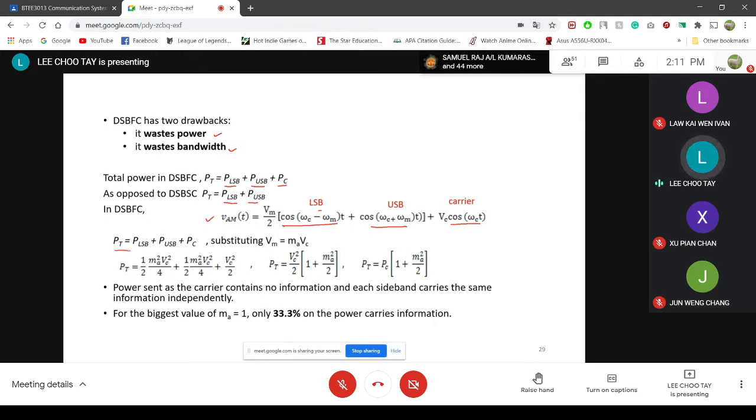So using this equation, the power in the lower sideband basically is this one. This is the peak amplitude of this lower sideband signal. To find the power in the lower sideband signal, basically take the peak amplitude, divide by √2 and then square it. For any sinusoidal signal, the power is equal to the square of the RMS voltage.